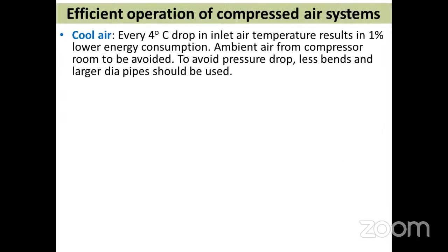Efficient operation of compressed air system. For every 4-degree drop in inlet temperature, there is 1% lower energy consumption, so cool air is better. So we need to get air inlet from outside the atmosphere, not from the compressor room. Inside the work area, the ambient air will be hot.